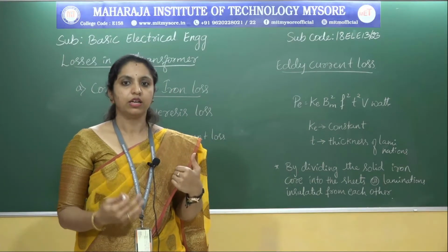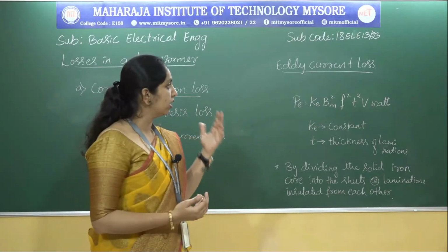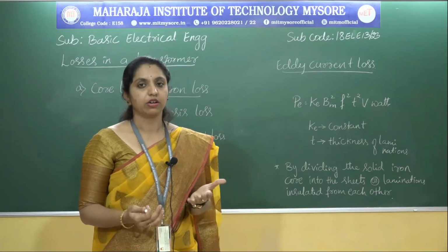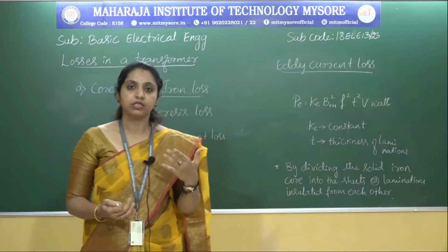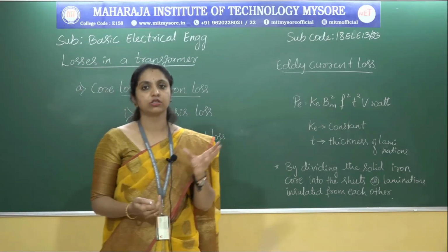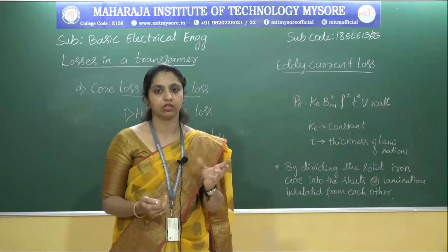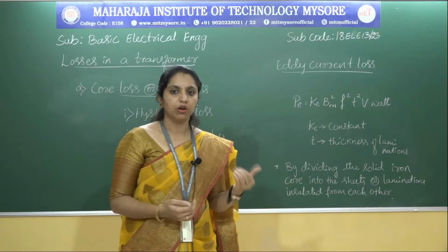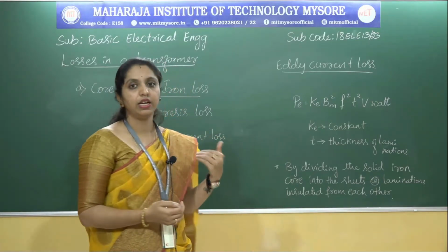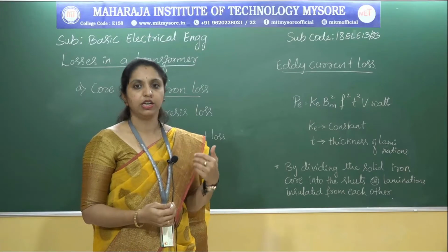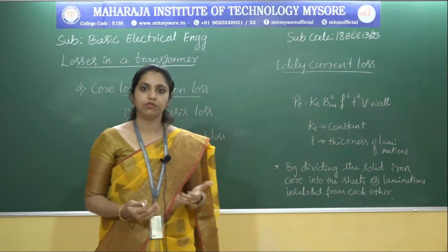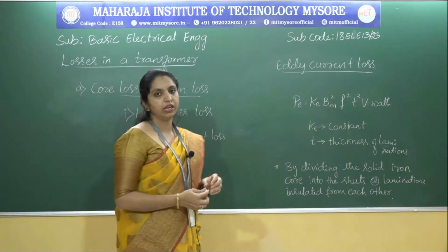Of course, this eddy current may be quite high, and since the resistance of the iron is quite low, it results in heating of the core and loss of power. So this is nothing but eddy current loss.